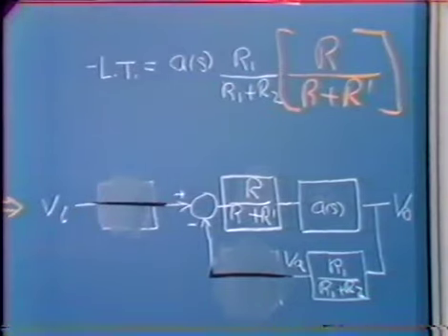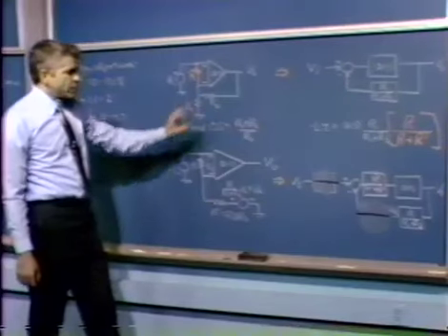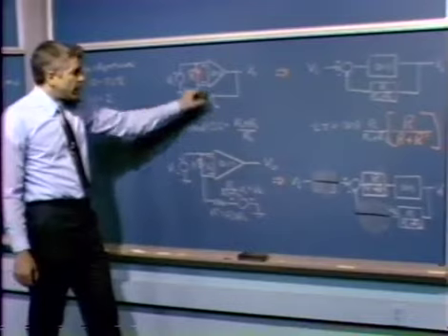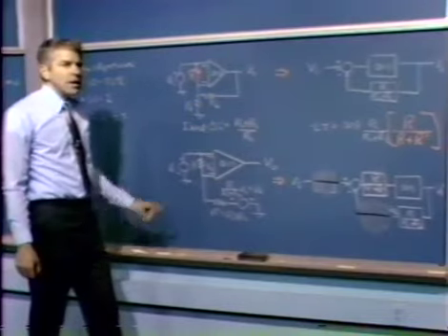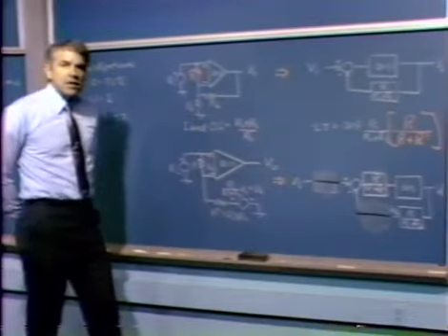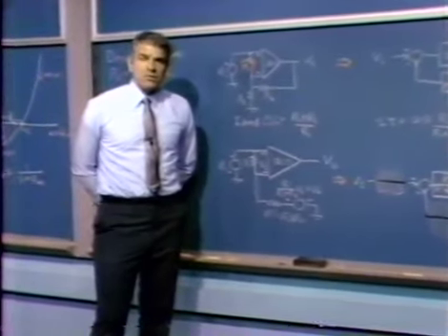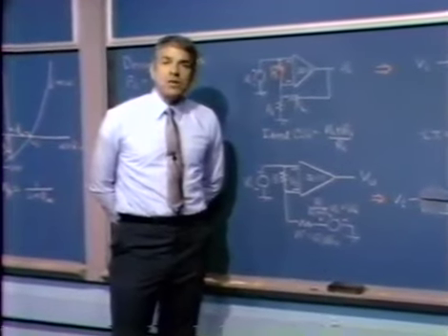And so if we had a system where we found that the system was inadequately stable, for whatever ideal closed loop gain we wanted, we'd be able to improve the stability by adding this one resistor. This is actually fairly frequently done. What we find out is that there are certain operational amplifiers sold, for example, that are not guaranteed to be unity gain stable.